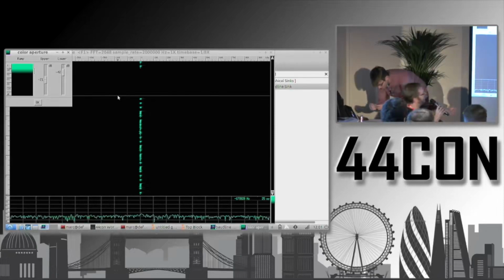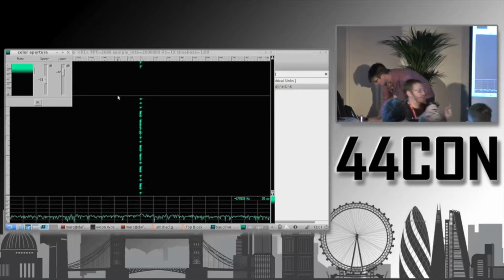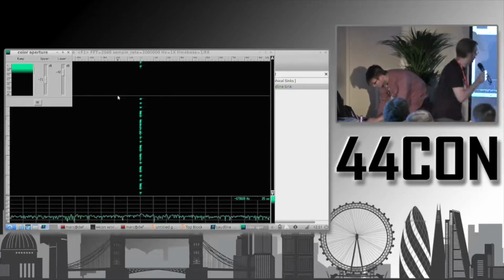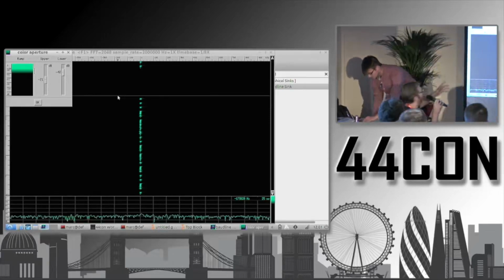And what's happening is that this is a type of modulation, or it appears to be, called pulse width modulation. And so this is a type of amplitude shift keying or amplitude modulation where the data is encoded in how long the transmitter is on. So in this case, we have what looks like a period of the transmitter being on for a short amount of time and then off, and then a different type of symbol which is on for a longer amount of time and then off. And so this is going to be likely either bits 1 or 0 there, and then the other bit 1 or 0 there. And so it's a pretty simple visual protocol to look at once we can tweak the color settings here.